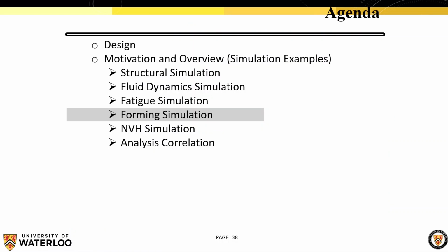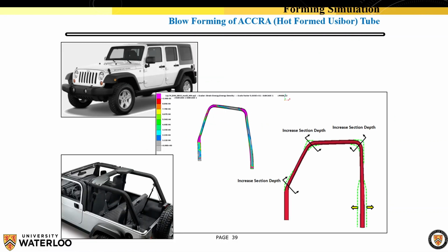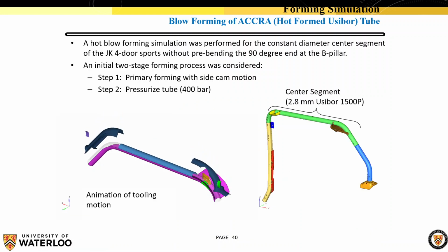Here's another example. I worked on a project back when a Jeep looked like that, where the structure of a Jeep has these bars that effectively maintain the roof from collapsing when you flip it over. In the event that you get in an accident, unfortunately, you'd tip over the car. So these bars run the length of the side of the car, and they're fairly difficult to make. The reason being is you don't want something that has some inherent kinks in it. If you've ever tried to take a tube and bend it, or even a piece of plastic tube would be very easy to do, you might imagine that if you bend it too tightly, it'll start to kink.